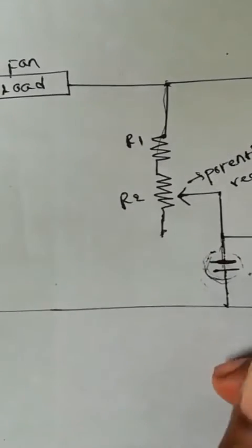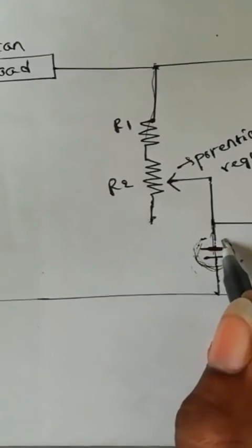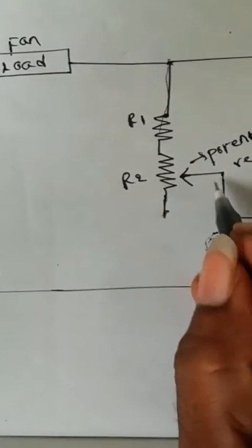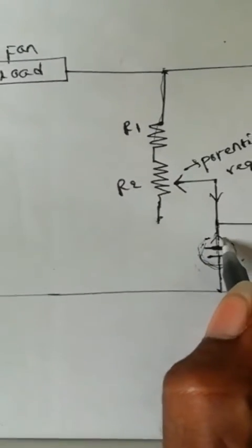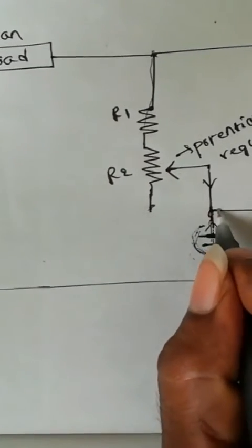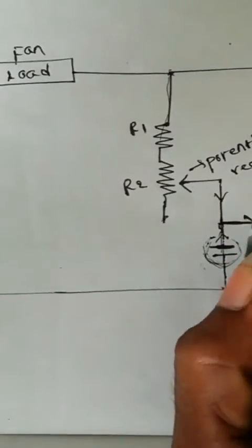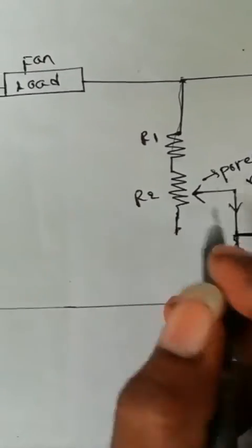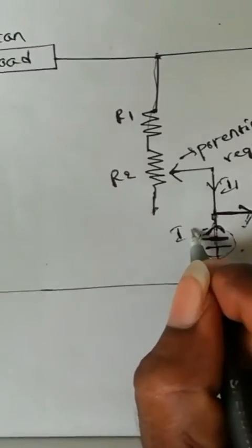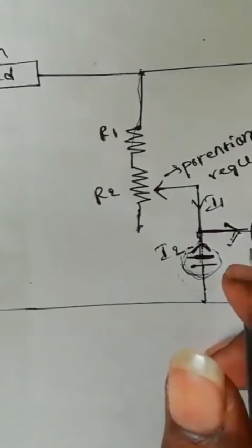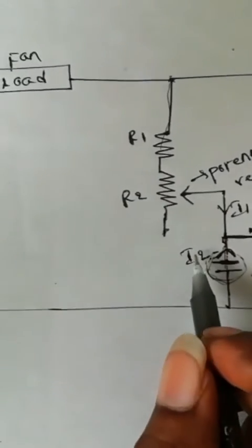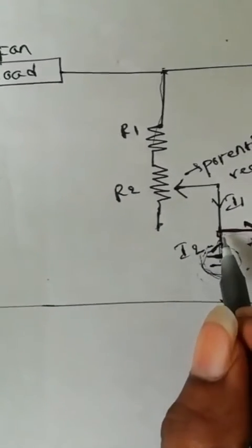Some voltage is developed across this capacitor, and we are also providing the 220 volts AC supply. So both of these currents have only one way to flow, this side only. These two currents, I1 and the current through our capacitor I2, combinedly flow this side.